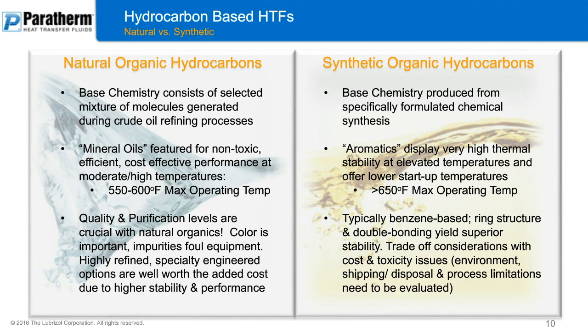One key point behind the natural organics, often referred to generically as mineral oil-based products: the quality and purification levels are very critical here. Okay, so color is going to be important. If you have coloration to these natural organic mineral oils, that's often going to mean that there's either a high level of impurities or a high treat rate of some kind of additives in there. And those are all considered impurities that will foul your equipment before the actual base chemistry breaks down.